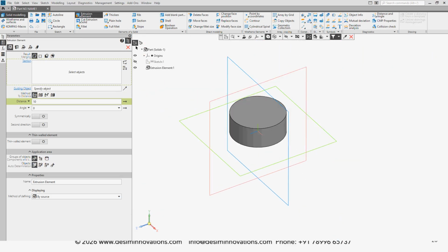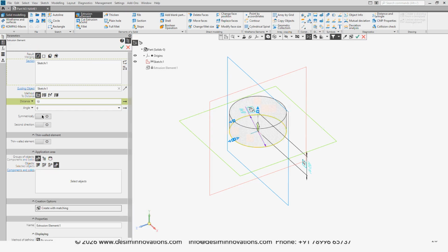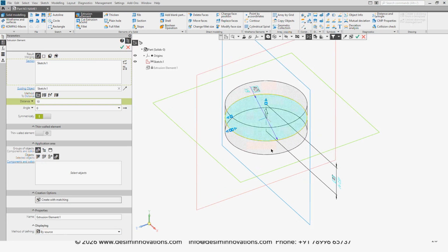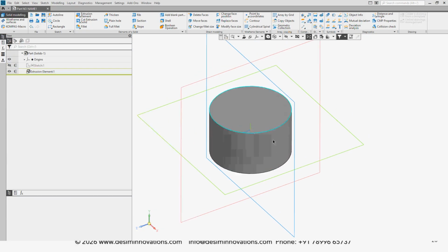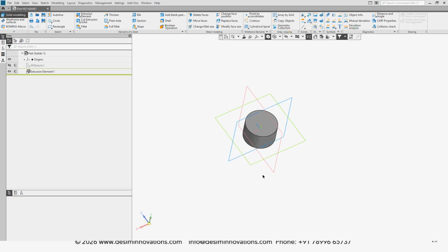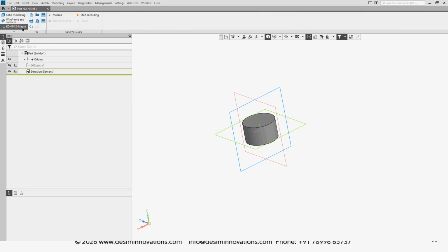As I am creating the blade, I will use the symmetrical option where it distributes equally across the full surface. I'll specify a thickness of 15, and it has created the hub of the propeller blade. Now I'll import a 2D airfoil profile. In order to import the 2D profile data and create a loft, I created one macro which can automatically import the 2D coordinate data and create the lofted wing or propeller blades.